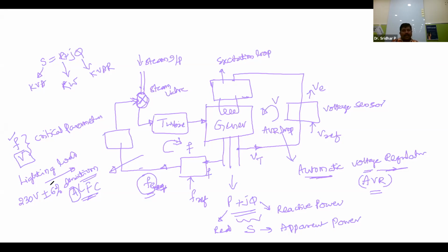And Amar Sai, you told that there is a relation between the voltage and the frequency. Now voltage and frequency may have a relation, but the relation is very poor. They are loosely coupled. Only if the variation in the frequency is very bad will the voltage change. The frequency has a tight coupling with the real power.